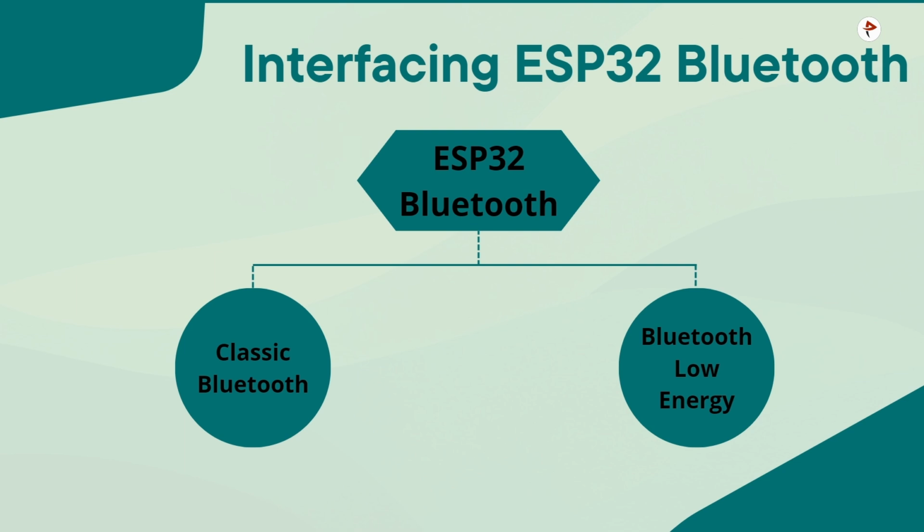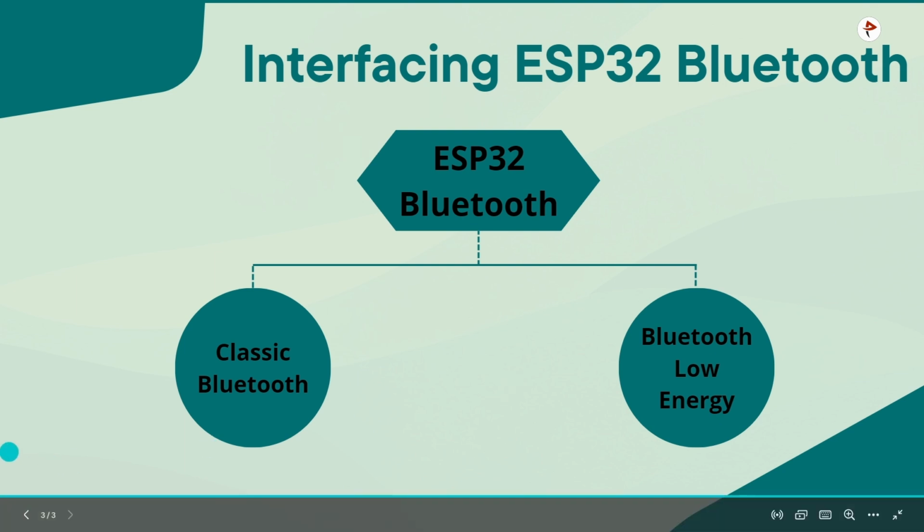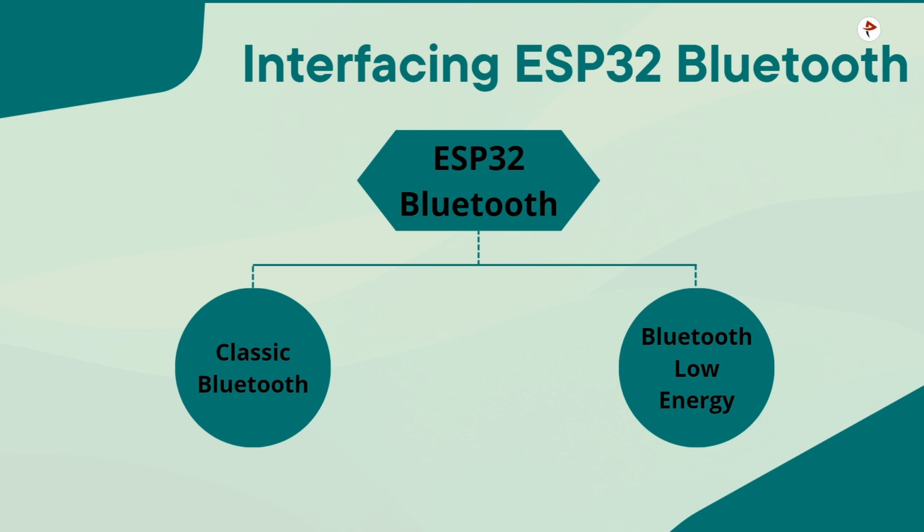So this library works similar to the serial library, but it is just with the ESP32. Some of the frequently used functions offered by this library are begin, available, write and read. So now let us write a simple code which transfers data between ESP32 and a mobile phone. To receive the data on ESP32, we are going to print the data on a serial port.